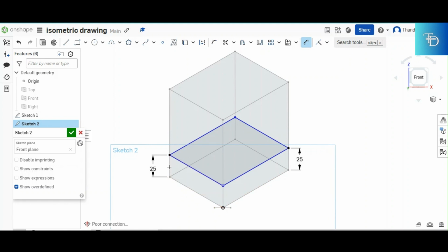You can mark your 50 millimeters anywhere. You can mark it at this line over here. You can mark it right there. It doesn't matter because the 50 is going to rotate also. So now you take your ruler, you mark 50 right there. And then the next thing you do, your 50 rotates, and right back to where it started. So now it's like you are building layers of the drawing before you put the actual drawing in there.